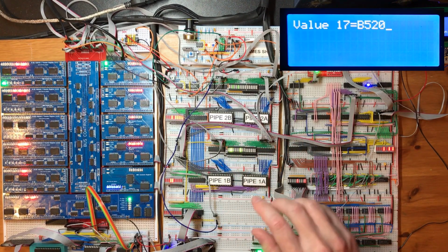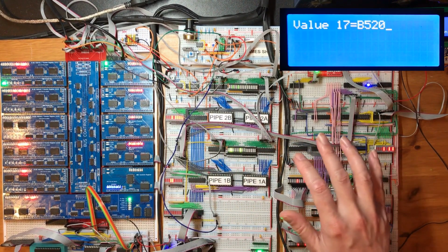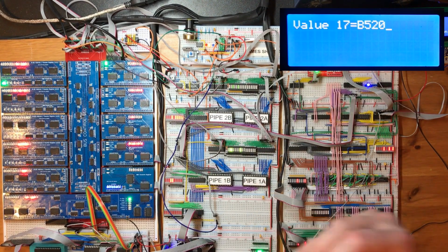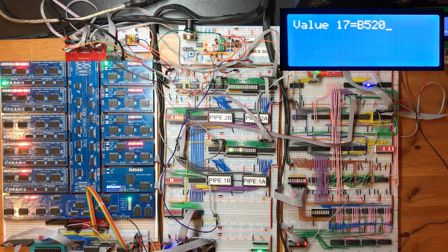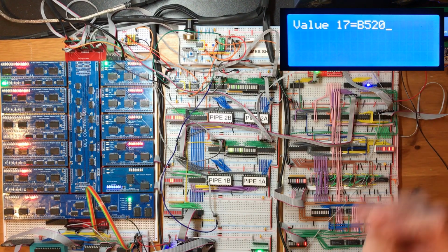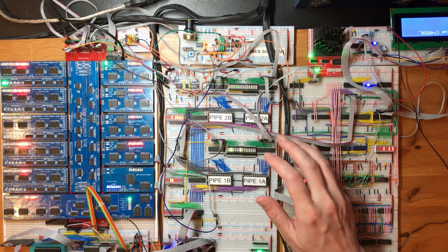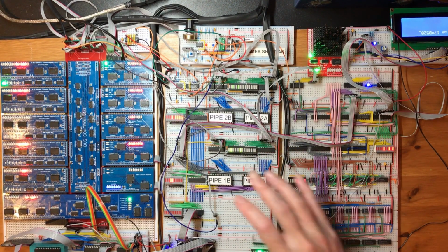Now the big deal is I'm outputting hex numbers. And I'm doing that because it's actually pretty easy. You can perform that simple subdivision of the bits, and 4 bits goes to each hexadecimal digit. But what we'd really like to do is be able to output those in decimal. And that's going to take a little bit of extra effort. What we need is a division and a modulus operation, and that's not trivial.